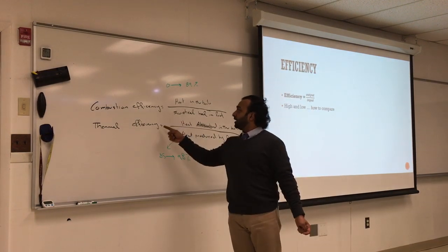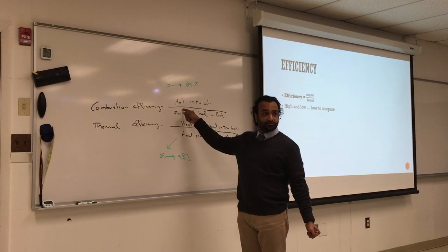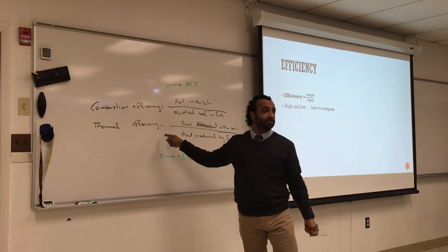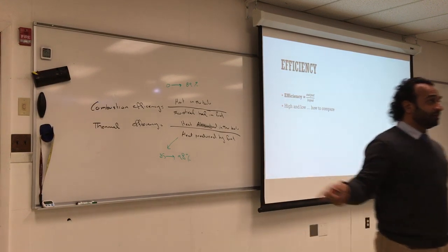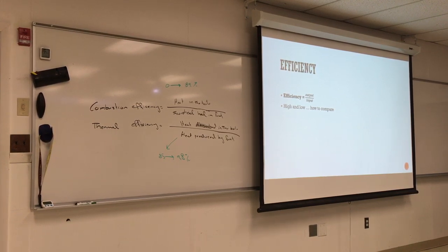Actually, the combustion efficiency is going to be kind of fixed based on how new the boiler is. You're going to go with the thermal efficiency, because that you cannot change. Thermal efficiency is the design efficiency, based on the heat exchanger in the furnace or the boiler, so it's how they designed it. When it's clean, it's going to give you this efficiency.